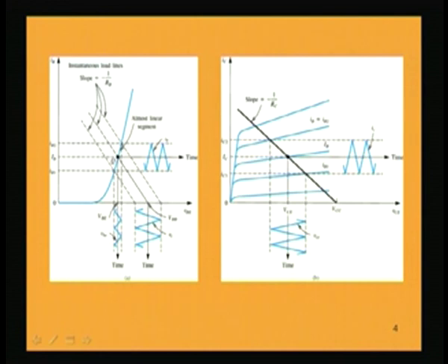The DC base to emitter voltage is V_BE, and the current flowing in the base, the DC current, is I_B. So, for that particular voltage, this is the current I_B. So, the Q point in the input characteristic defines the DC voltage between base and emitter and the base current I_B.